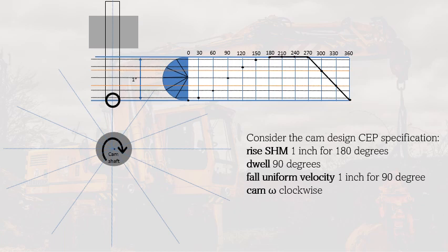After that, we're going to draw now the concentric circles, beginning with the 0 degrees. Take note that the trace point is the center, that's why it is at that point. So that is our first trace point. The second trace point, which is at 30, is the intersection of this horizontal line to the follower. We're going to draw a semicircle until that point, concentric with the first circle. So the intersection of that circle and our 30 degrees here will be the second trace point.